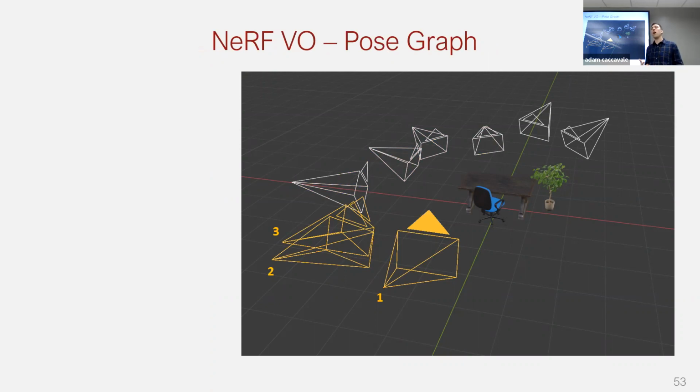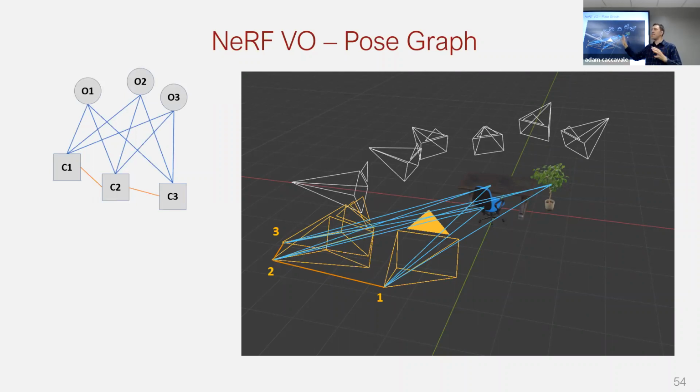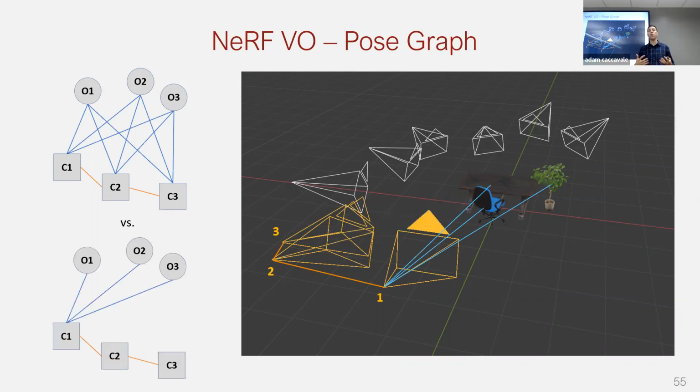Now, a very natural expectation is that if you're estimating multiple objects in a single camera image, you will get multiple relative poses, one for each object from that view. But if I have multiple views and I do this, plus I have connections between each camera view, all those different connections are going to look like a tangled mess. Because there are cycles in this object, which is called the pose graph, and because these connections are noisy, you actually need a second level of optimization known as pose graph optimization. However, I can avoid all of this and estimate fewer variables by always using a minimal pose graph for each of the windows in the sliding window framework. By that, all my poses are always just relative to the first camera view.